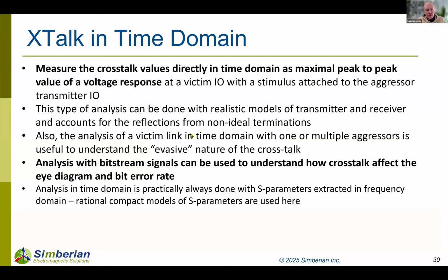So, crosstalk in time domain. I'm getting very quickly out of time. So you have to measure crosstalk. You can measure crosstalk directly in time domain as the maximal peak-to-peak value of the voltage response.